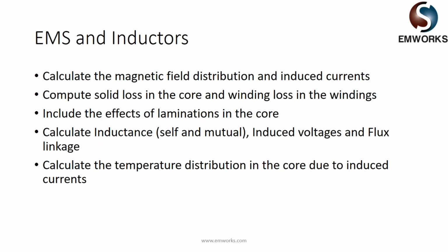And finally, one can also couple EM simulation to multiphysics thermal, where one can calculate the temperature distribution in the core due to the current, or I would say the eddy currents that are formed due to the AC signal or any kind of transient signal in the inductor.